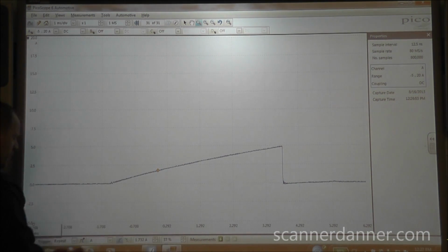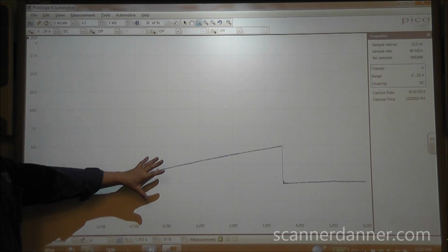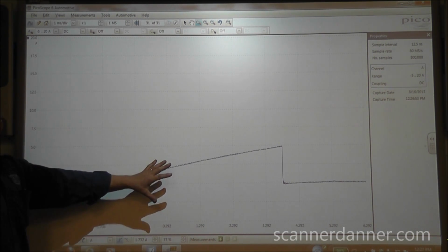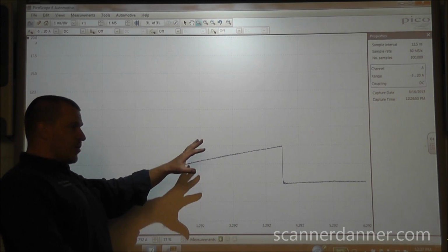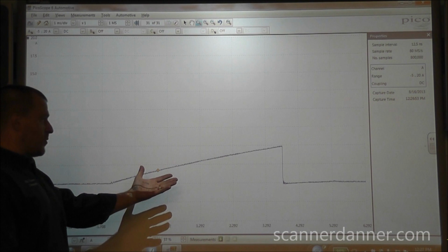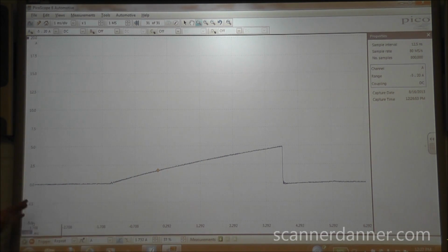But I like repeat myself for that reason, rather than auto, is it will hold the last event on the screen. Now that can throw you off if you're a rookie, because you think you still have a signal, the car's running or whatever, and you have a signal on the screen and it's frozen. It's not live, even though it's still running. So just be aware of it.